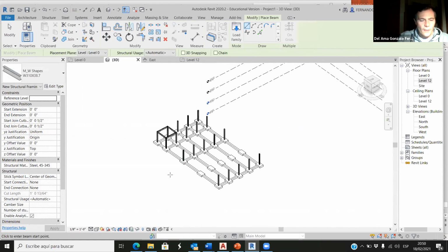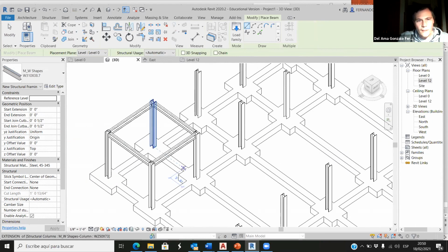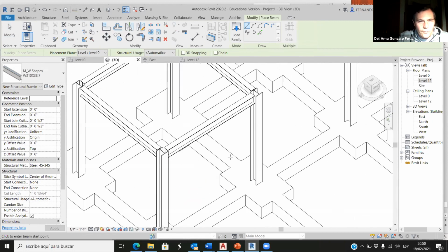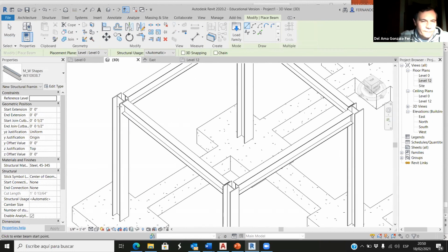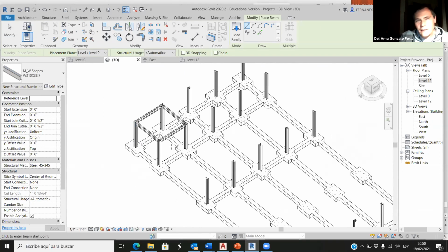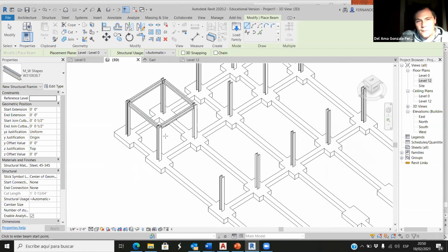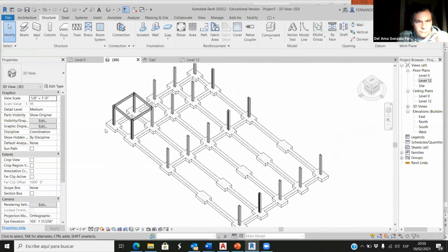Okay. So we have 4 beams here. We have to calculate that. Okay, so we have a column, then we have a beam. But without calculating anything, we should understand that the beam for this span should be lighter or should be smaller than the beam for this large span. Okay, so we have a 12 foot span. The beam should be smaller than a 24 foot span.